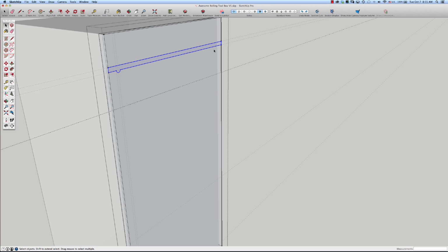A lot of times if you're not careful, you'll grab something in the background, and if you don't notice, you'll have to step backwards quite a bit. M key for move, Option Alt key for copy, and we've got 4-inch spacing, and I went from the bottom edge, so I'll take the top down, and actually I want to go there, so 4 inches. And I'm just confirming this by looking at the spacing in the bottom, so that gives me my 4-inch spacing.